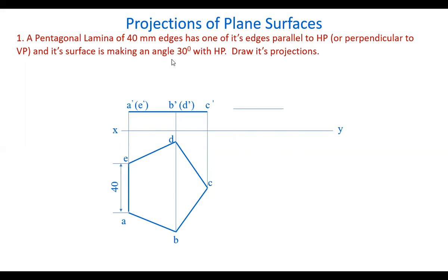Now, I want to tilt this like this. That means AE is kept in the same position and point C is lifted upwards like this. So draw a line here at a 30 degrees angle, and the same front view length is marked here without any change, no change at all. So the front view is drawn here. Now mark these same points on the front view: A dash, B dash, C dash, like this, we have marked all the points.